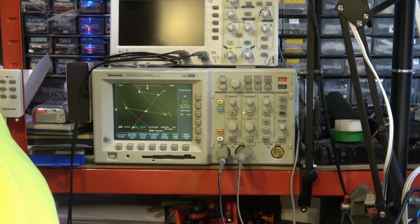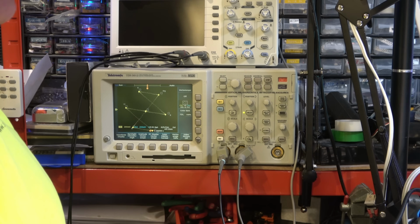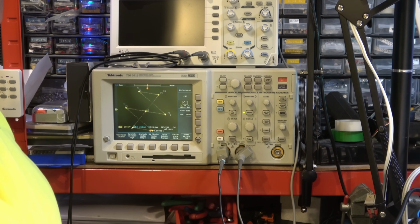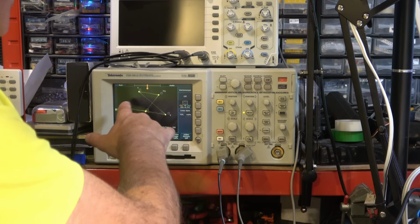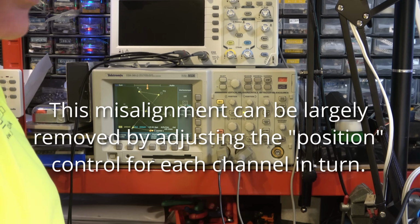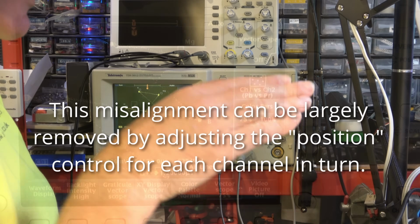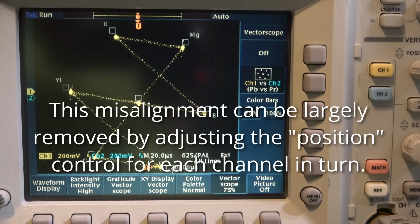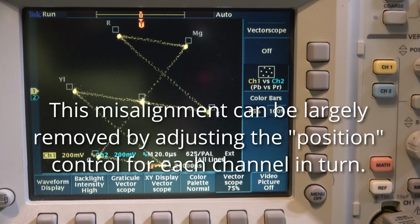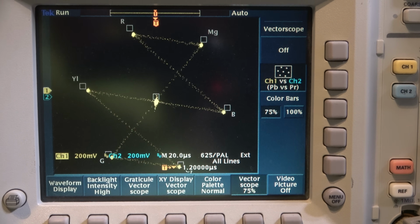Okay, that has helped. So we may have had a bit of a problem with signals bouncing up the BNC cable there, but still all the colours are shifted down from their proper locations. Which is not something you can adjust on the time-based corrector, because of course this is its own internal test pattern, so its adjustments are only for signals that it's processing, not for a color signal that it's generating.